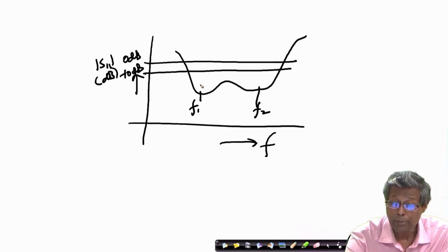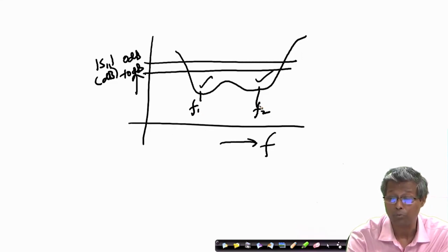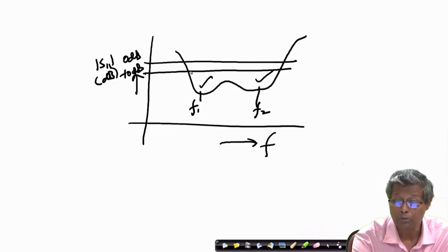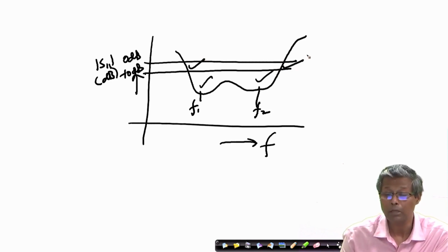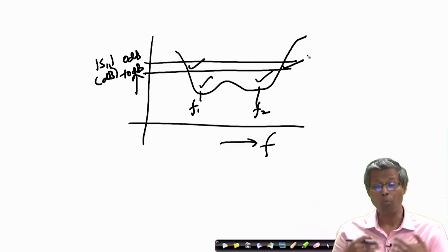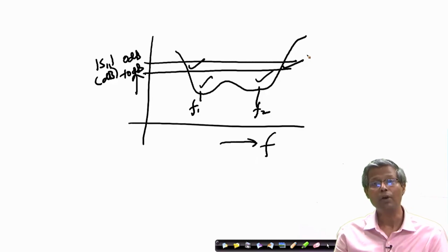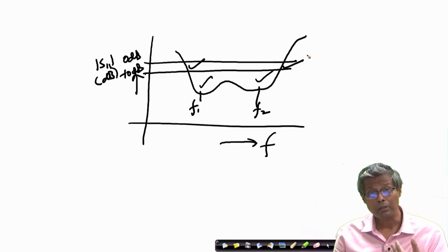So, similar to the previous case, we can ensure that similar radiation characteristics will happen at f1 and f2, and therefore, the pattern will stay uniform across the impedance bandwidth, which is from here to there. The pattern is going to stay the same across the impedance bandwidth. So, these are the ways in which we can design a better antenna structure, and we can have control over the radiation characteristics of the antenna, by utilizing the nature in which the modal indices affect the modes and the design.